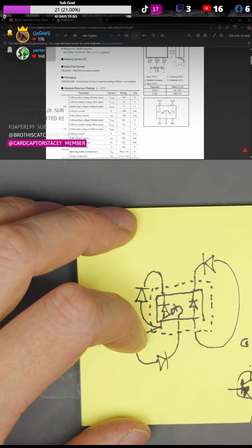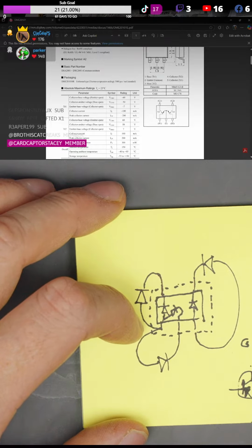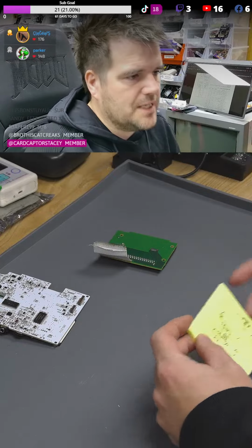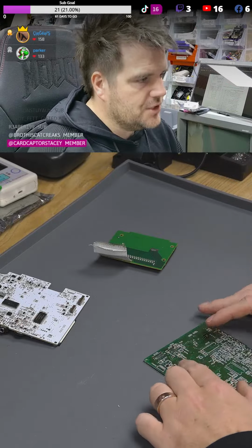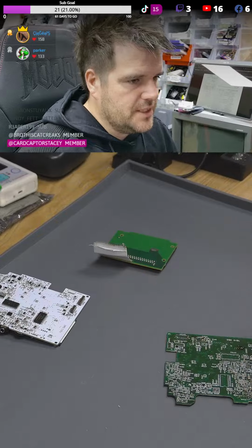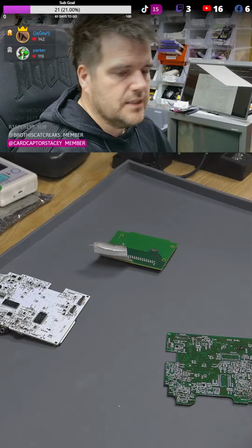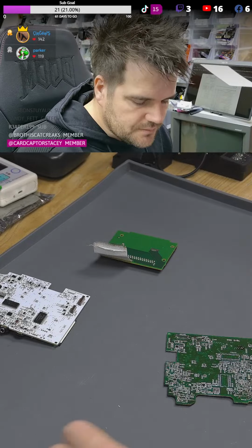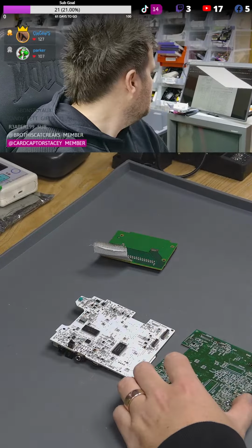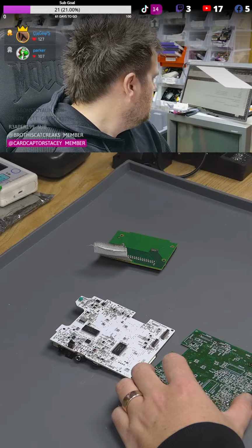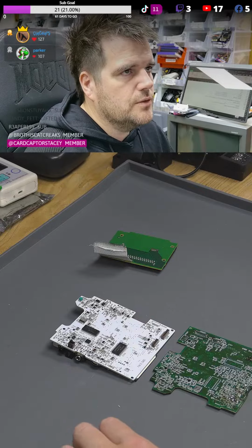So for now, I'm just going to leave this. I'll figure it out. I don't think you guys are that bothered if you see it being discovered. I'll tell you when I find it, but that's the process I'm going to go through. I'll keep looking for packages that look similar. I'll probably take this chip off and put it through the component tester in every orientation, and basically, I'll figure it out that way. I'll find out there's going to be transistors in there. It's just a process of elimination and time. So for now, what I'm going to do is make sure I've got notes on the Excel sheet of all these parts we haven't identified yet, and then I'll come back to them. There's only like 3 or 4.